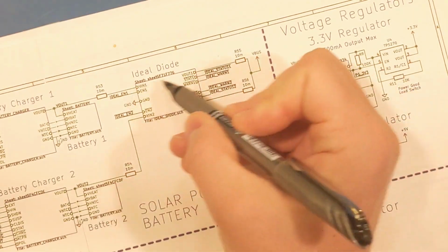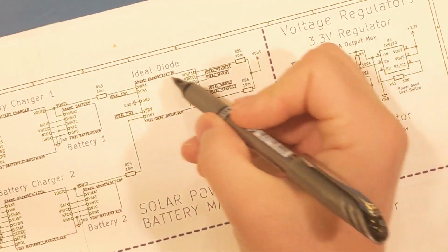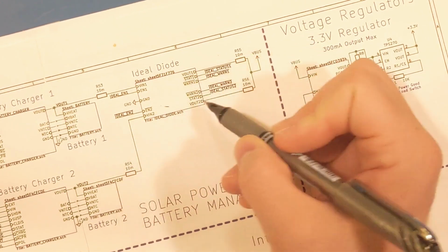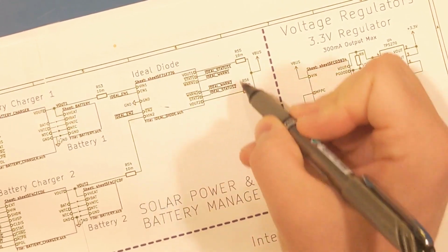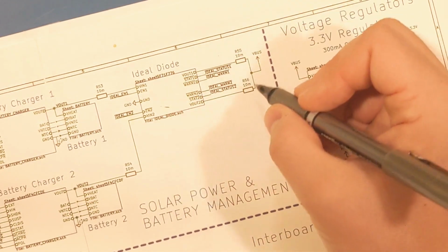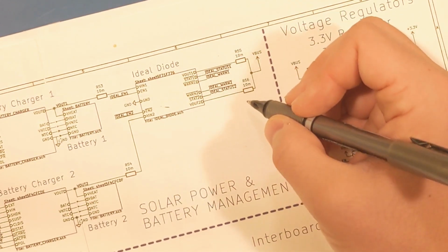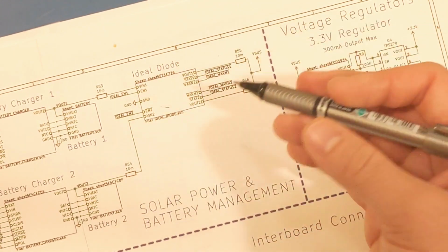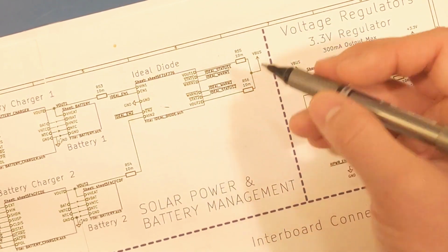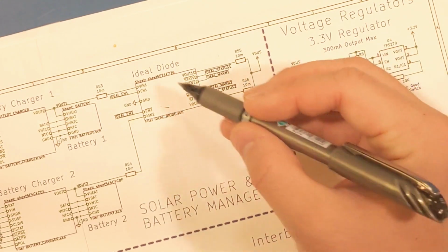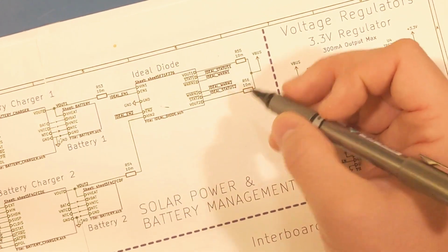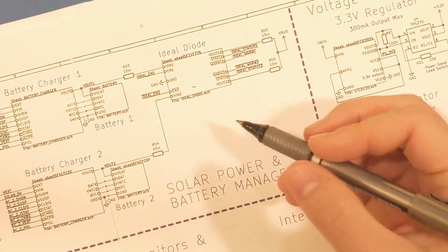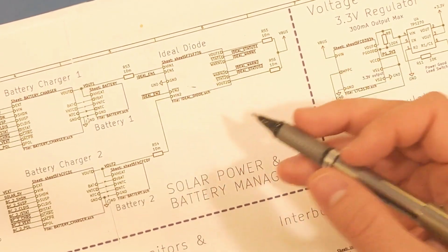And looking at the ideal diode circuit, really this is just a wrapper for that LTC4415 because both of these V-outs are connected together, and I connect them together just through these 10 milliohm resistors so I can easily disable one side of the circuit if I want to during prototyping. Or I can also measure the current that's coming through the diode at this point. That's why I have a whole bunch of these 10 milliohm resistors, just for debug and development purposes.